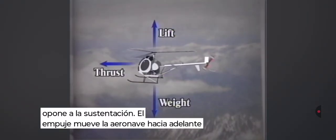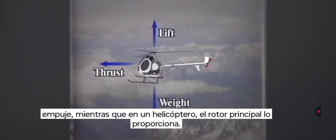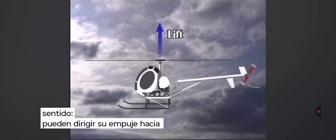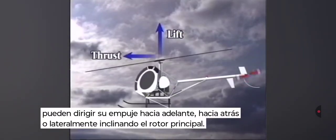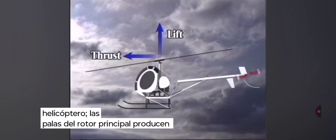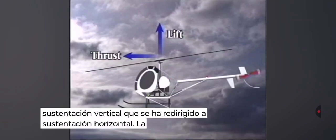Thrust moves the aircraft forward through the air. In an airplane, the propeller supplies thrust. In a helicopter, the main rotor provides thrust. In fact, helicopters are unique in this respect. They can direct their thrust forward, aft, or sideways by tilting the main rotor. In practical terms, there really is no distinction between lift and thrust in a helicopter. The main rotor blades produce both. Thrust is simply that part of vertical lift that's been redirected into horizontal lift.